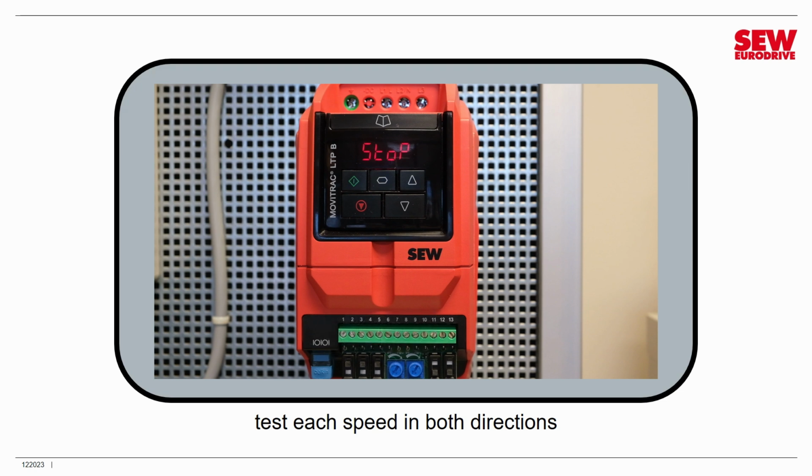So what is going to happen, since digital inputs 3 and 4 are both off right now, as soon as I turn digital input 1 on, the VFD is going to start running, because that is my first set point, preset 1. Just a heads up here, I'm not showing the actual motor here. You can just look at the display on the VFD. That will tell you what speed we're running, and I do assure you the motor really is turning at those speeds. So we're going to enable the drive.